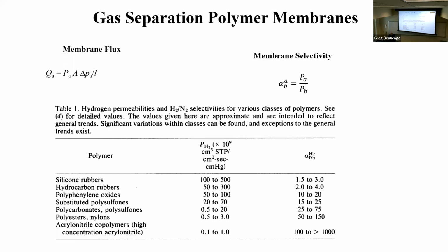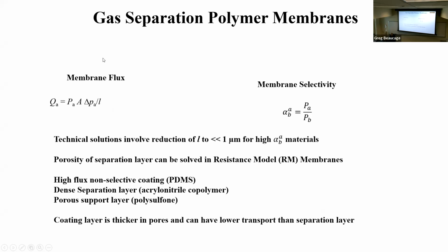In other words, pressure is going to cost something, especially if you're talking about like 60 megapascal or something. A pump to do that, like 600 atmosphere, is like $100,000, just a small scale one. And also you need the strength of the membrane. If the pressure gets too enormous, you can't drive the flux just with pressure. You need some pressure, but you can't do that, the thing will fail. Also, the pumps cost too much. So you have to somehow balance these things out, and the way to do it is with the thickness. So everything's going to be made as thin as possible.